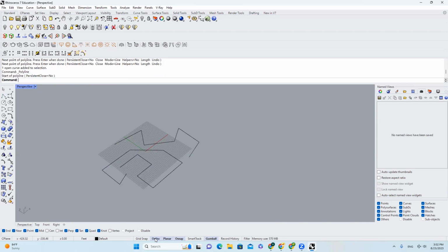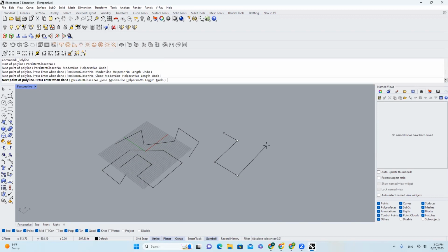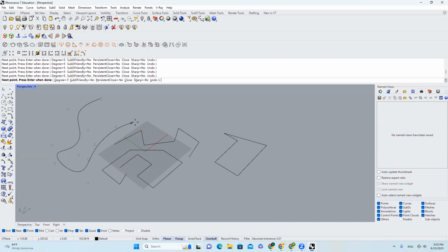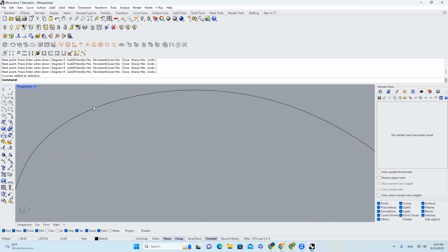Same, if you click off the orthogonal and just use this tool again, if you hold shift, the orthogonal mode will come back. And if you just let the shift go, because right now the default is non-orthogonal, you can draw things freely. And that's just what the polygon can do, and also the control point curve, which can draw a completely, extremely smooth curve, which means that no matter how much you zoom in, it's going to be a very smooth curve.